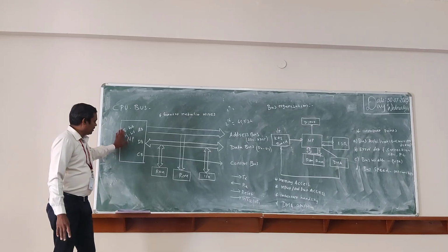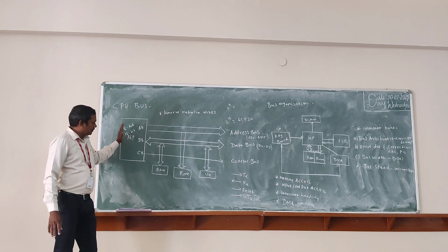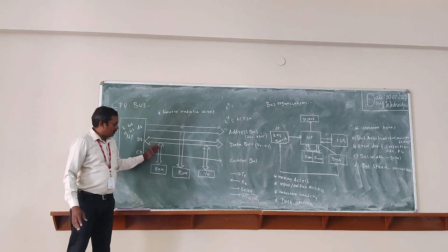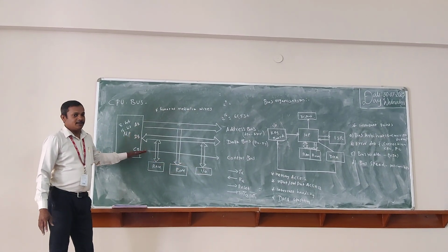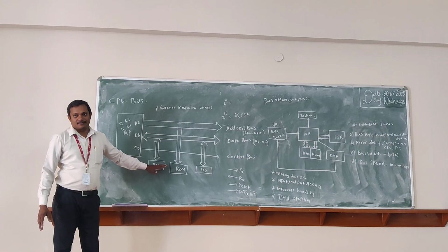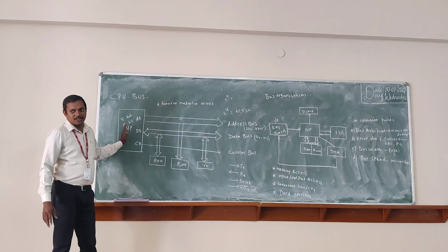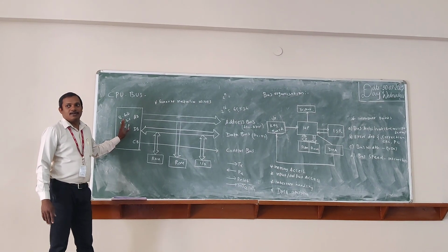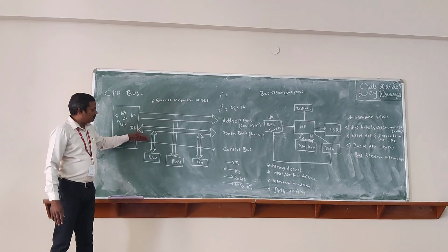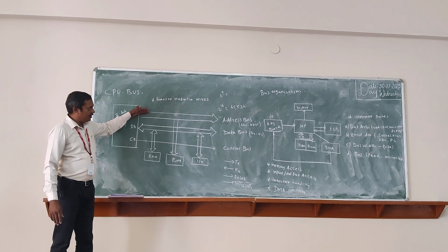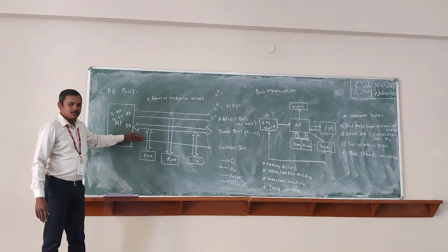Okay. So as I emphasized here, this microprocessor does not have any peripherals. That's why we have to integrate these peripherals externally. You have to connect these peripherals externally to the microprocessor. So in simple words, the microprocessor is a CPU, central processing unit, or the brain of the computer. So here you can see three different types of line. First line indicates the address bus, the second one is the data bus, and the third one is the control bus.